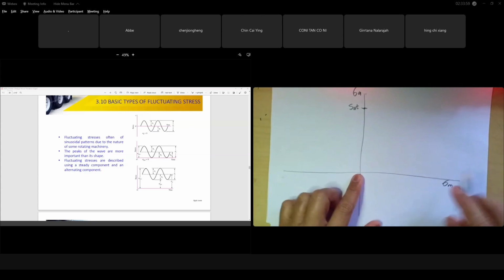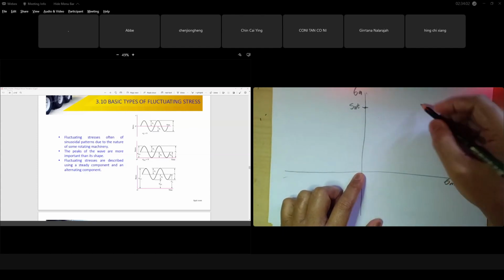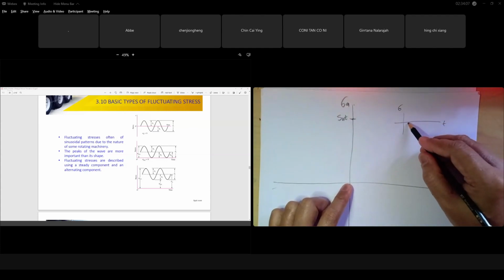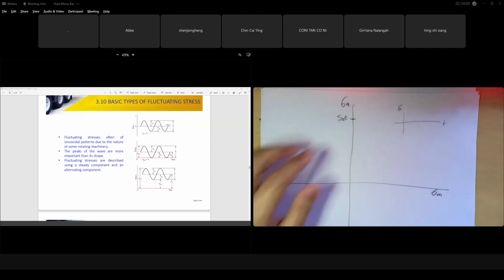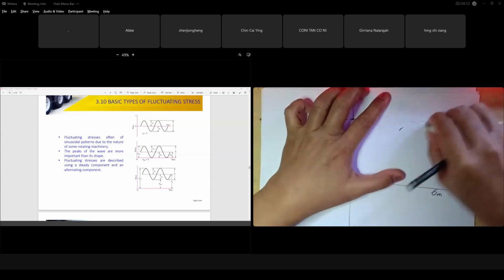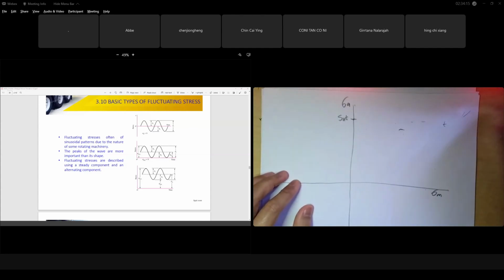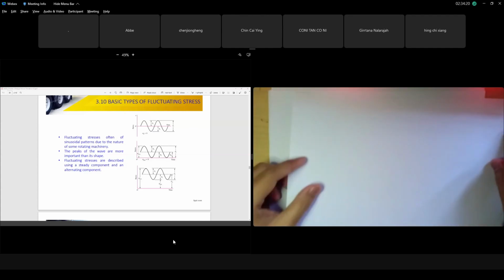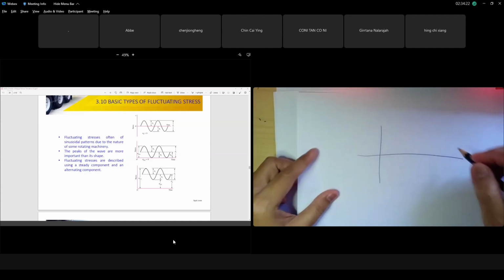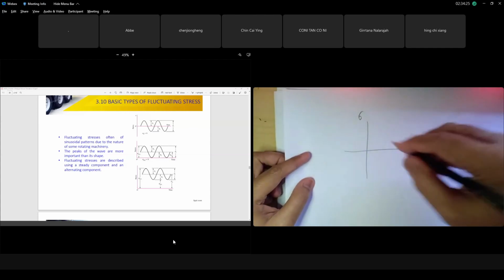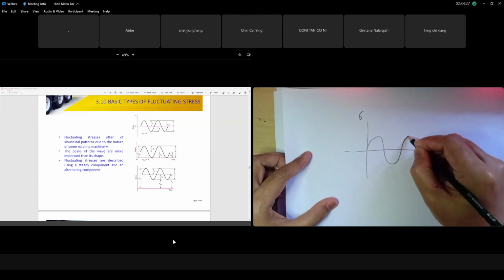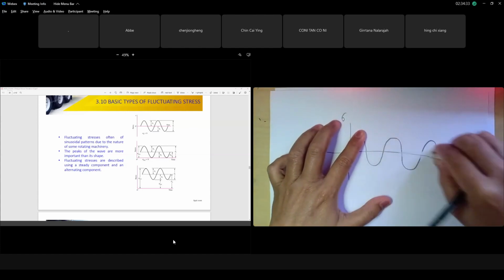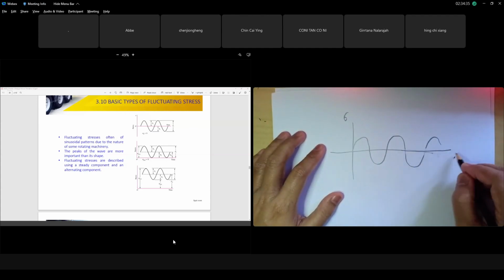If you have a plot of your stress over time, where the mean is 0, I will draw it so you understand. All your points along the y-axis are where your stress case is like this. Your stress over time, the stress that you calculate over time, is like this. Completely reversed. This is another fluctuating stress, but we have max, we have mean, completely reversed like a shaft. Most shafts are completely reversed through time.